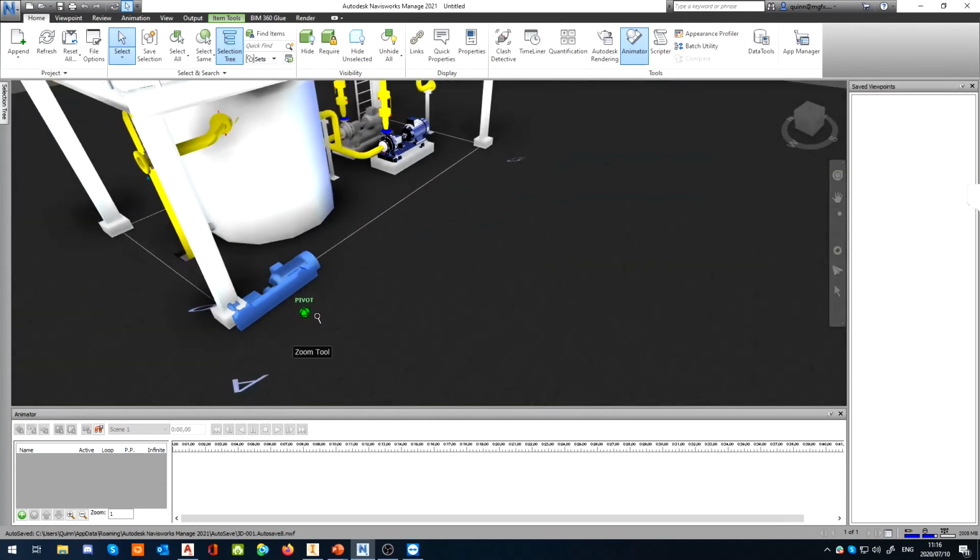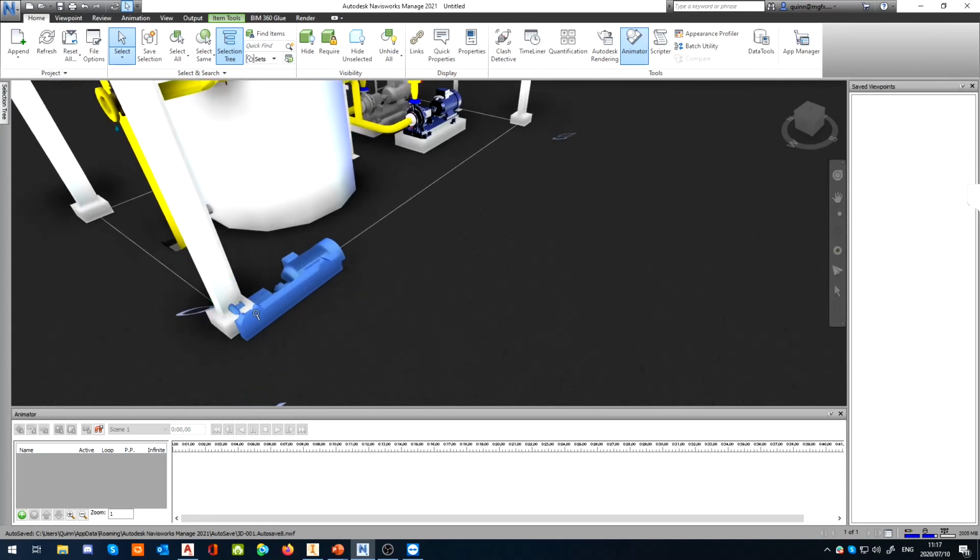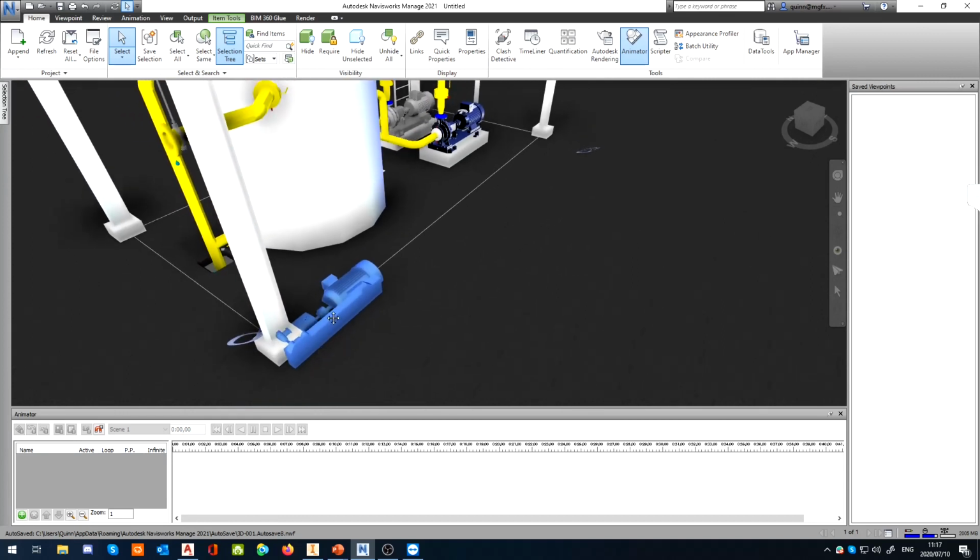Now, this is the problem with it. It inserts it via its own XYZ coordinate system. So there is a way around this, in that you can specify its XYZ, but you create a separate IAM file. So if you've used Inventor before, basically what you do is create an assembly within an assembly, and then you move it to the correct XYZ location in that assembly.